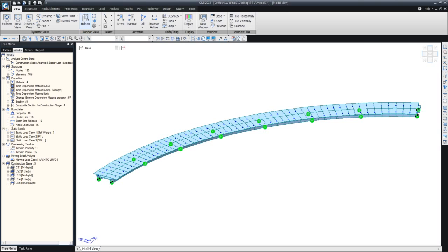There's a very good point made out here: when you post tension, are the temporary supports restraining any vertical movement upwards or creating secondary effects? Yes, that's a very good point. If our members are restrained by the temporary supports, and then the post tensioning is done, there will definitely be secondary effects in the structure, because it is at the end an indeterminate structure.